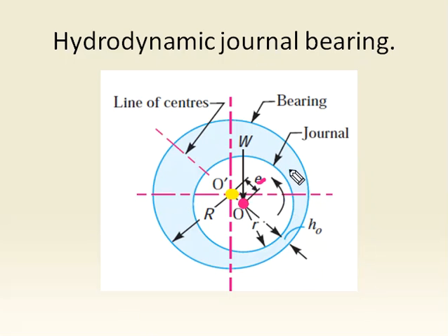That load is distributed through the oil. The load is received by the oil and distributed throughout the body, so automatically the load is transferred to the bearing. So the oil is responsible for carrying the load. It also provides the lubrication effect, and distribution of pressure is also possible using this oil.